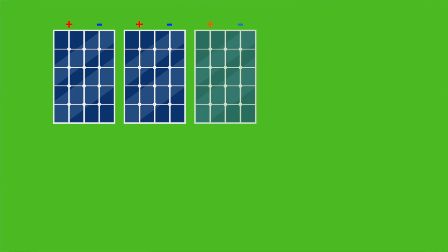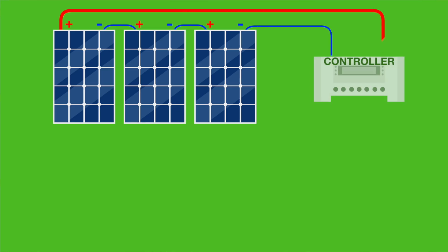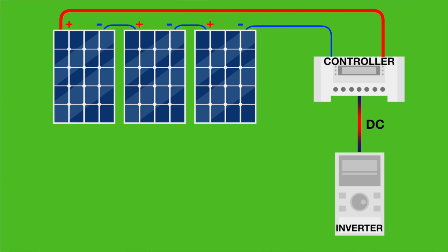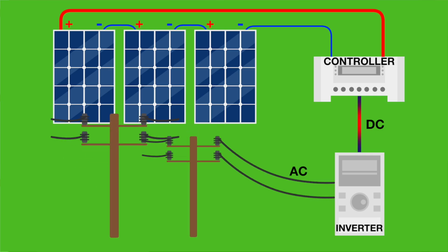Can you walk us through how all of those components work together and really focus on those photovoltaic modules that we see? Absolutely. Starting at the photovoltaic modules, as the solar radiation hits each module, it's creating a DC current flow, creating electrons to move, similar to a battery where you'll have a plus and a minus on each module. We connect those modules together, plus and minus, to create strings of DC, and we'll connect those together to aggregate that power. Then we convert it to AC electricity through the inverters, and we bring that out to the grid.